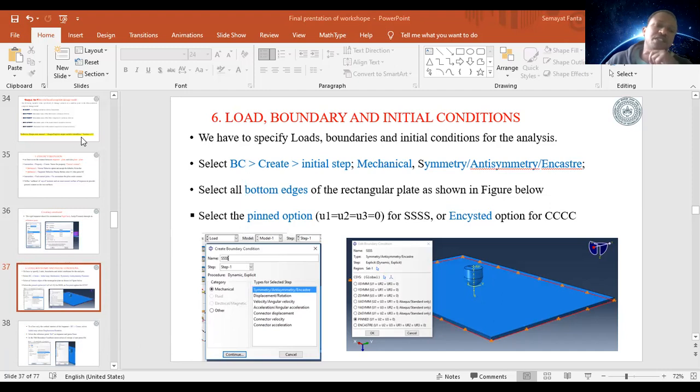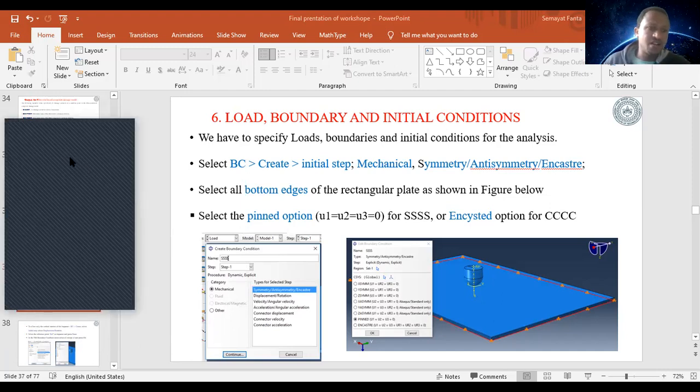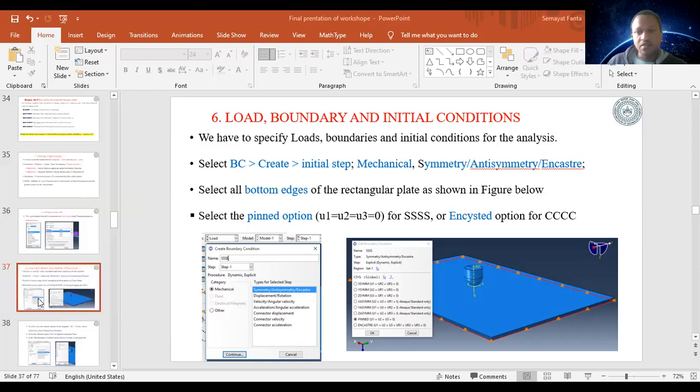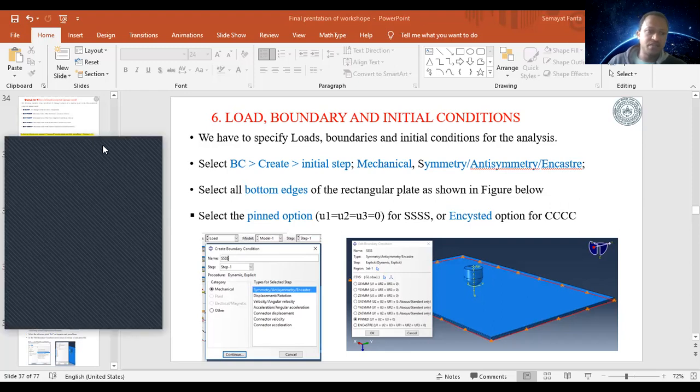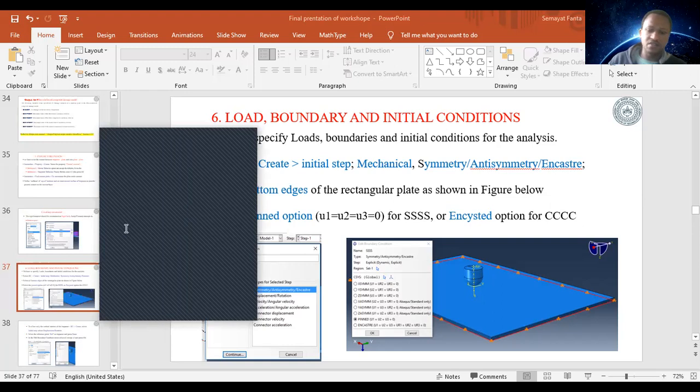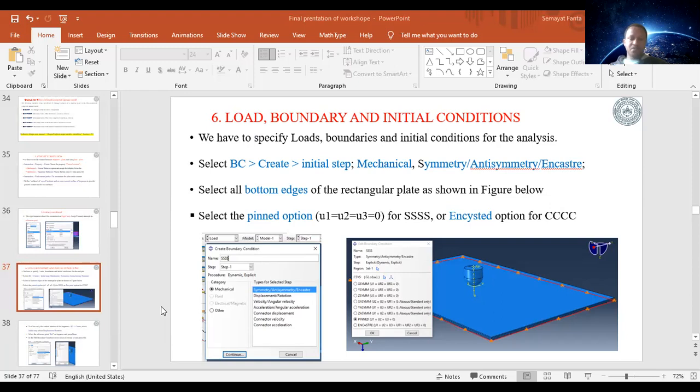So we provide the impactor motion from the initial mechanical velocity through this same point, a velocity of 2 meters per second. The velocity is not specified in our program, so let's take 2 meters per second, low speed.